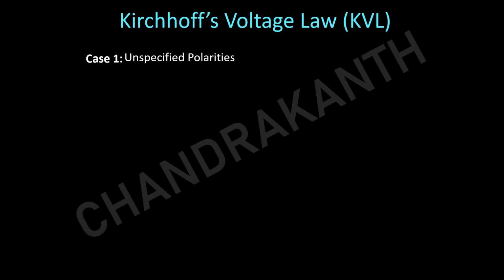Now, how to apply KVL for any circuit? Here we are going to consider two cases. One is unspecified polarities. For KCL, we need not think about the polarities because the importance is given to the current directions. Since voltage is associated with polarities, we need to consider those polarities while applying KVL.